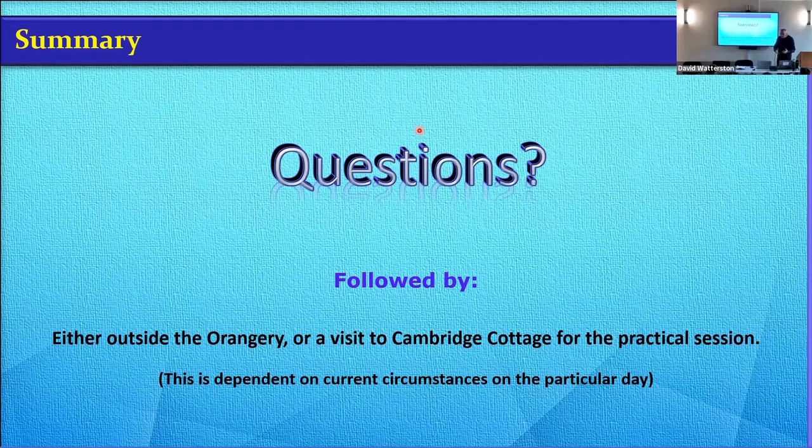And by survey quality I mean whatever they're going to draw from that might never affect you. But if they're doing high precision stuff, it would, because it wouldn't work. It needs to be proved. So somebody could come in here with a helicopter or a little drone, fly it all. But if he hasn't measured something that you can check it to, it's a waste of time. It might be good enough for what you want to do, but I would treat it very lightly.